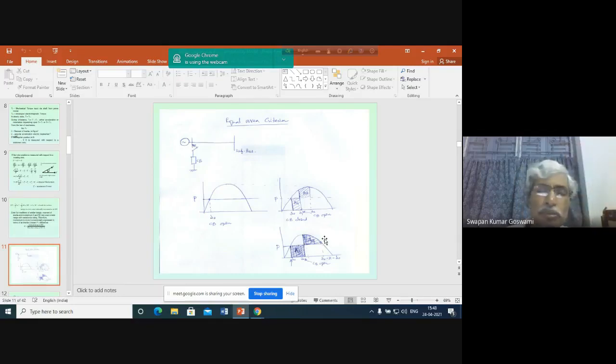We shall not be observing the second swing. We shall not be discussing the second swing because it will be rather difficult to discuss from this diagram. We have to draw it again in a separate manner. Okay, but we are assuming that if the generator becomes stable in the first swing, it will be stable in the subsequent swings as well. This is our assumption, and under this assumption, we can say that the generator will become stable.